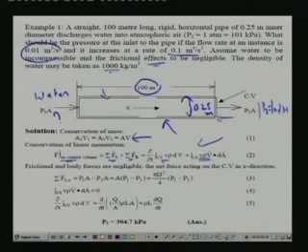Now the mass flow rate is constant at any given instant, and the velocity at this point is same as velocity at this point. So the net momentum flux out of the control volume is 0. That means this term is 0 for this particular problem. And since we are neglecting frictional effects, and since the pipe is also horizontal, there are no body forces also, so this term is also not there. Then the surface forces in x direction is simply because of the pressure difference at the inlet and the outlet.